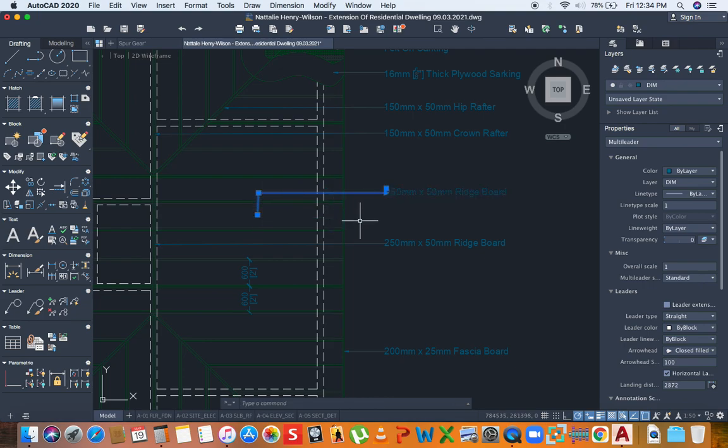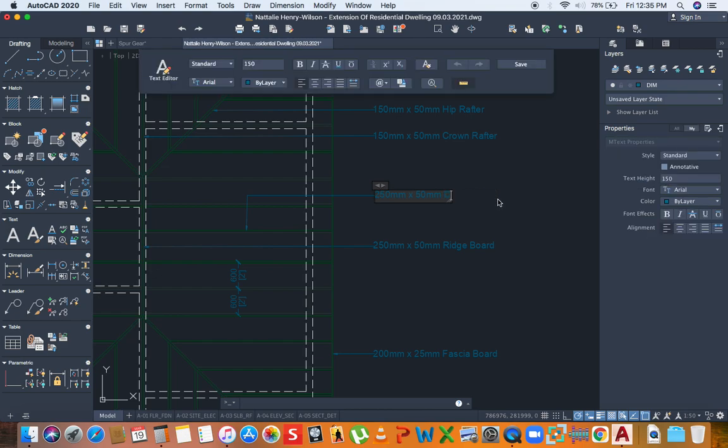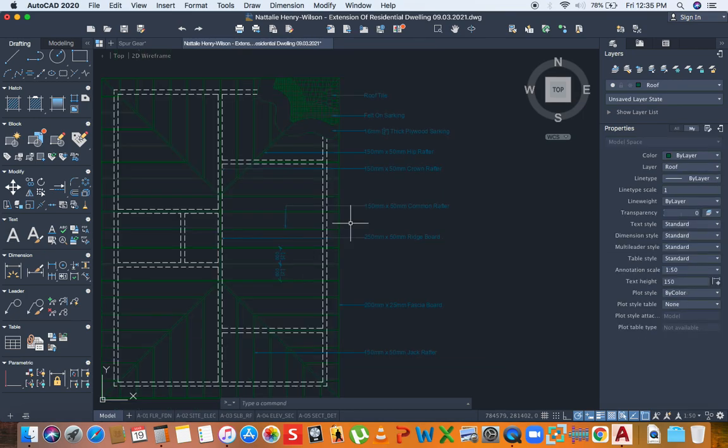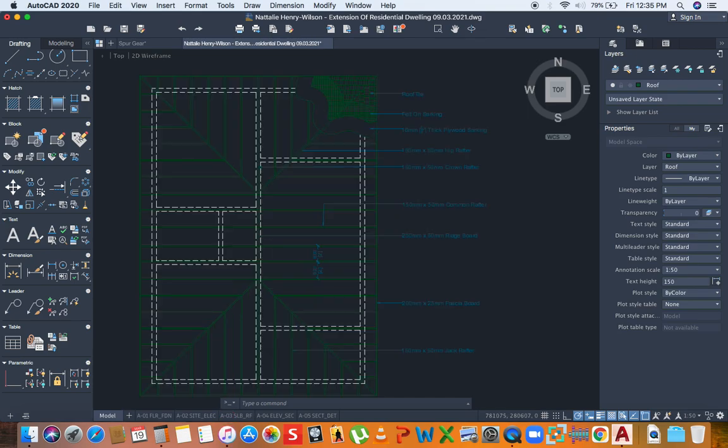Alright, there we go. So this is a common rafter that it's pointing on. And that is the size for the common rafter, so they would know what size boards to buy. And the length will vary, as you can see. The length of the rafters are varied, so you have to measure the rafters before you go ahead and purchase the board.